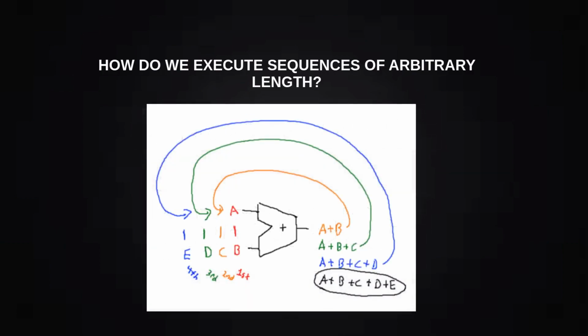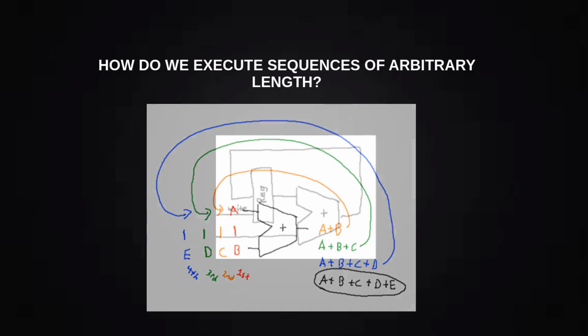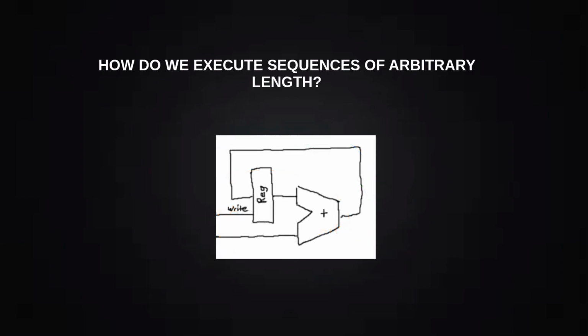Using just a single adder, we can tell it to add the first 2 numbers together, then add the third number to the total, then the fourth, and so on, so long as we have numbers to add. Now, since we're dealing with time, that means we're dealing with state, which means we need registers to implement this sort of circuit. So, simply by adding a register to one of the inputs, we create a sort of accumulator that can hold the intermediary answers while the circuit is calculating. We can clock this register every time we want to add a new number, and just provide that number manually.